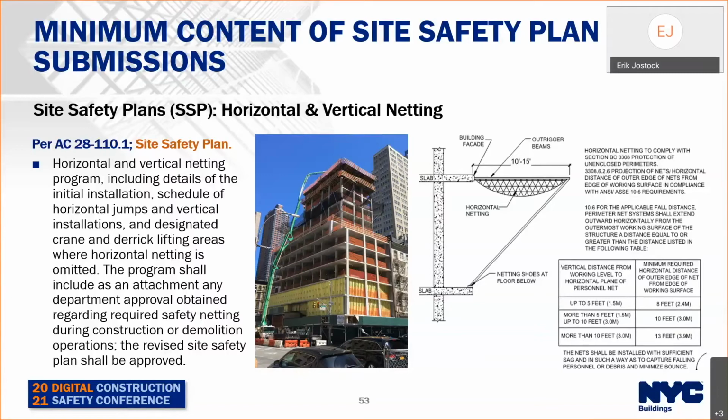Please note, no permit is required for the installation of safety netting systems in accordance with the section. However, a permit is required for alternative methods, including but not limited to cocoon systems and climbing formwork, which we'll cover later in the presentation.